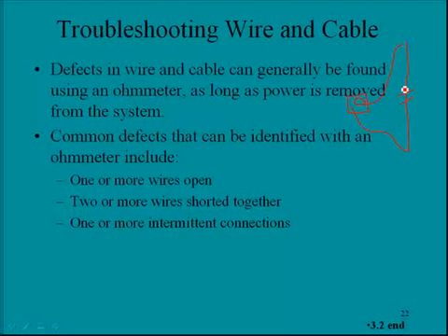An old electrician's trick, sometimes if you have a wall outlet, and let's pretend that for whatever reason voltage is not getting to this outlet, there will be a circuit breaker that's associated with this, and usually what a technician would do is they'd go to the circuit breaker and they would measure the voltage at the circuit breaker to ensure that voltage is in fact there, because maybe the circuit breaker is popped. But these wires will go to this particular circuit.